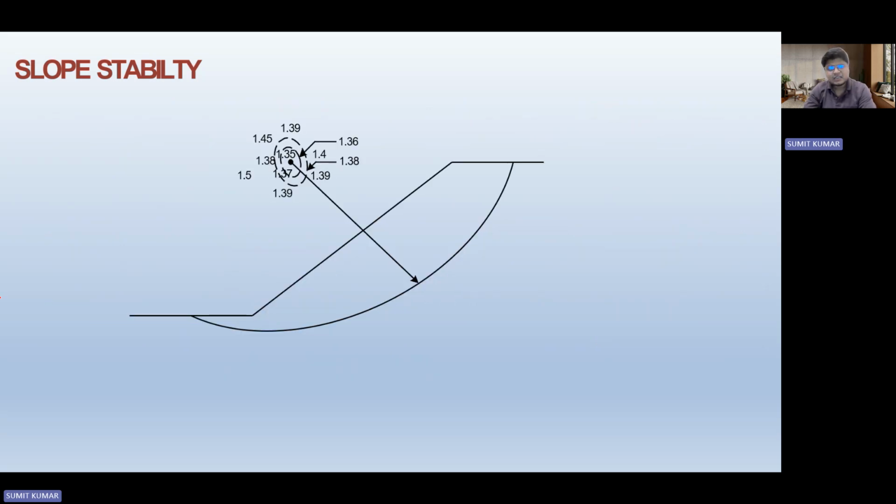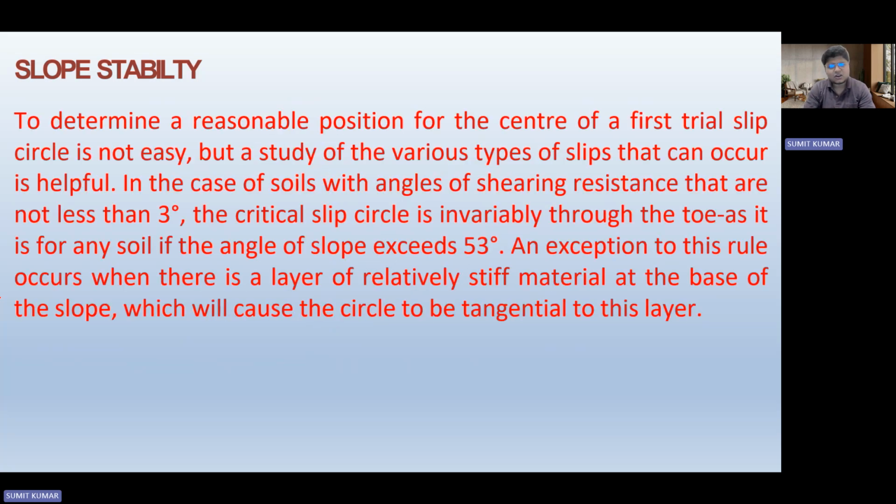Now over here you see that we have considered the thing, and the different circles have been drawn and the factor of safety is also stated regarding the same. Now again over here some more points are mentioned on how base failure, face failure or surface failure could occur in slope stability analysis.